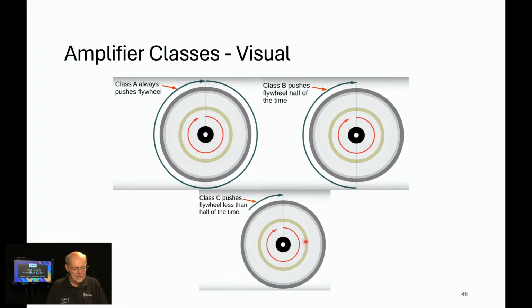Let's look at class C, for example. So we're just going to push it a little bit, but that coil and capacitor, the tank circuit, are going to keep on giving each other energy and absorbing energy, and the circuit will continue to oscillate. Oscillate probably isn't the right word, but it's exchanging that energy back and forth at the resonant frequency. I guess oscillate would be the correct word. So that can be a good thing.